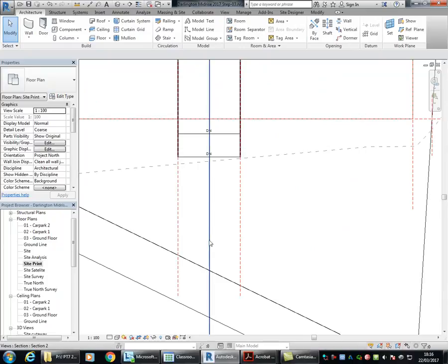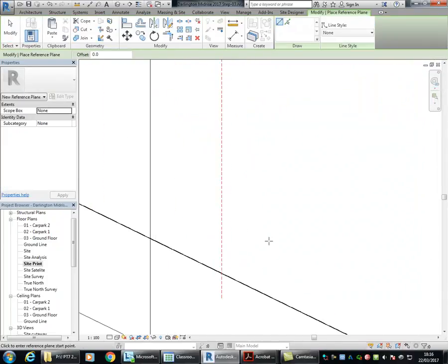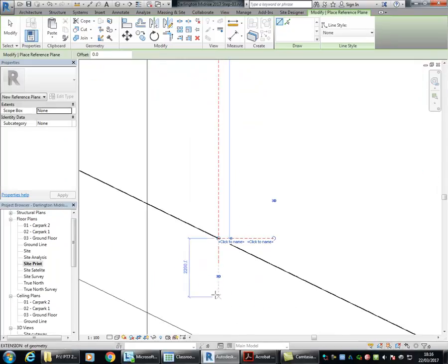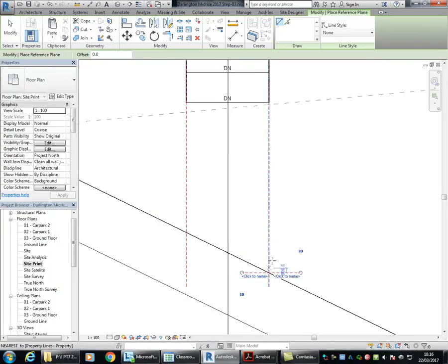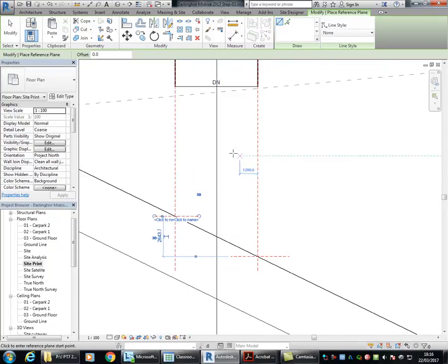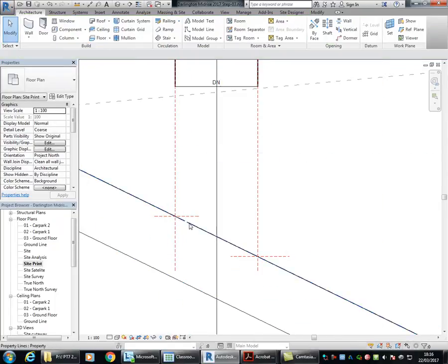But because it's not, probably the easiest way is to draw a reference plane at the intersection of that reference plane coming from my ramp, and make it horizontal. So with that horizontal plane, I know this is the far point. I'm going to need another one for the near point. Right, so just by drawing those two reference planes, now I can locate the boundary in my section.